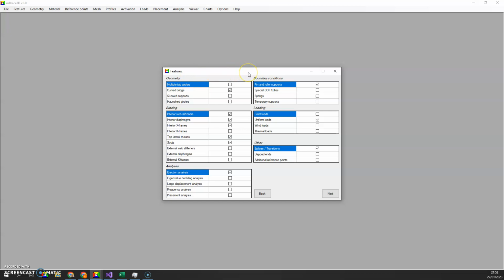Hello and welcome to this tutorial, which is addressing the issue of the brace forces during deck placement of a curved tub girder bridge. This is actually an important issue for curved tub girders, as the brace members are primary structural elements, and the design forces, in other terms, the maximum forces they will ever see, is actually during the placement of the wet concrete.